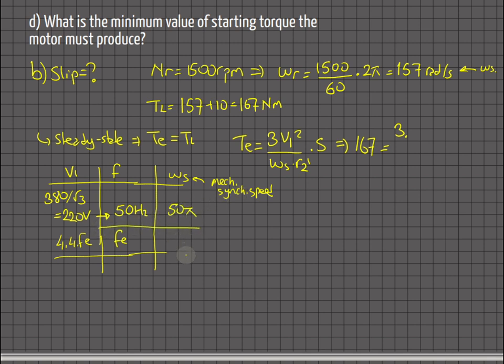And if I increase it, for omega s here, the voltage should scale similarly. It will be 220 divided by 50 pi times omega s. So I don't know the actual operation speed, but the relation of the voltage with respect to synchronous speed will be like that, as we have the 50 pi to 220 volts ratio.